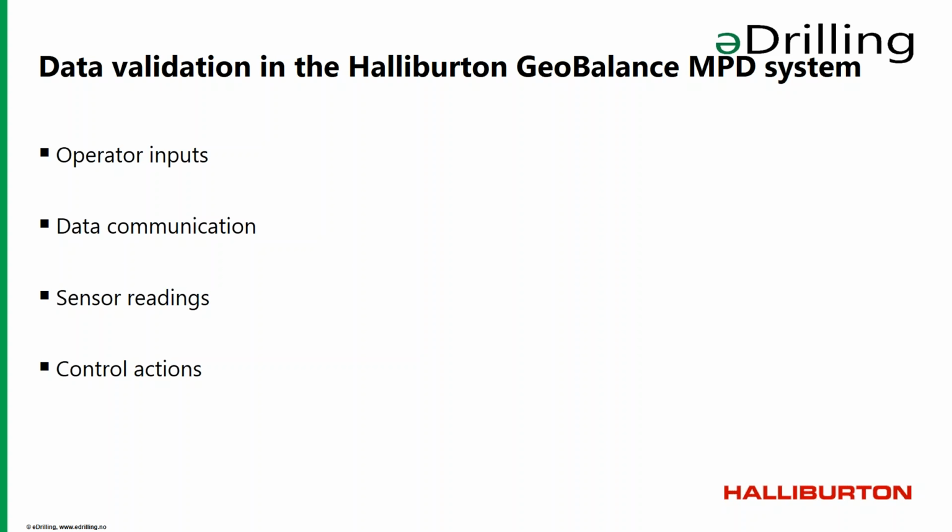Also, without the data validation, you would not know if the data communication has gone down. Then you would be reliant on the operator noticing it, and an operator, if he gets a lot of telephone calls or there are a lot of things going on around him, it might again take a while. So it's important to have data validation to ensure that the input that you get into the system is correct, and if there is anything wrong, either the system tells you that you can't run in automatic mode, or you'll get a warning telling you that something is wrong and you need to take an action.